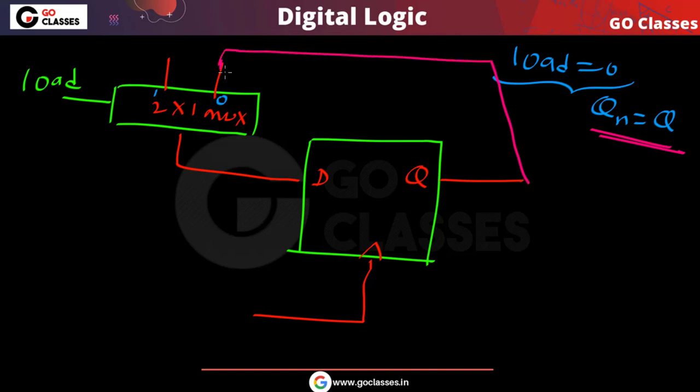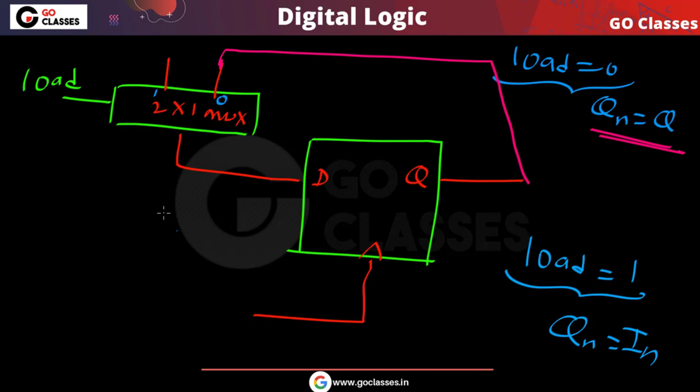So we can connect it here. And when this load is equal to 1, we want q next to be equal to in. So we can put this in here. Now you can notice, when this load is 1, then this in will be stored. And when this load is 0, then the previous output q will be stored.